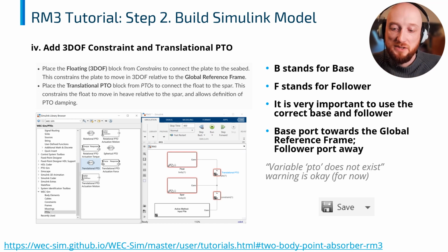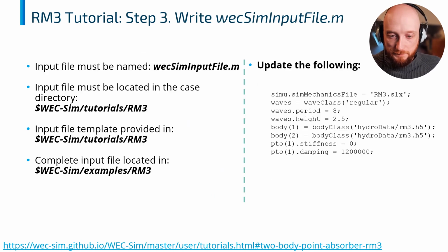So a couple of points to be aware of. You notice B and F on these blocks. It's important to ensure that the B port, the base, is pointing towards the global reference frame, and the follower port is pointing away from it. So once you've added those blocks, you can join everything up and then hit save, and it'll resave the SLX file, and then you can close that window and we're ready to move on to the next step.